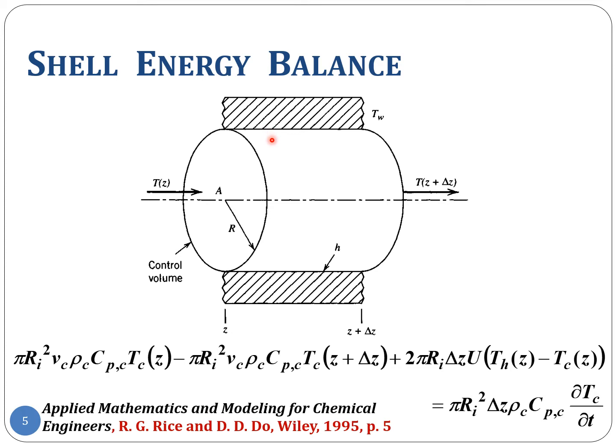I hope it is understood clearly that for pure convection to take place, there has to be a bulk flow, and from the solid surface to the fluid at this interface, at this circumference, essentially the perimeter, right? So here there is no bulk flow of any kind, and therefore the mechanism by which energy can be picked up from the wall boundary by the fluid is exclusively conduction, exclusively molecular energy transport.